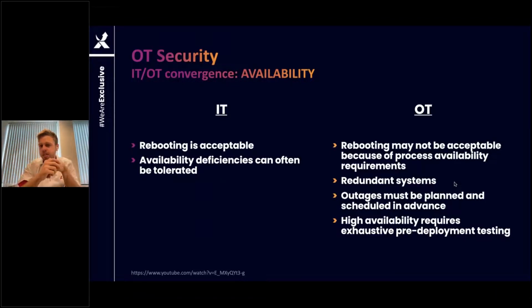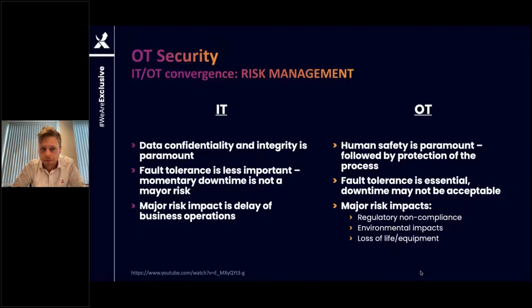You cannot restart an OT system right away. It must be planned in advance. And also the last point, high availability requires exhaustive pre-deployment testing. If you want availability, these systems are so well tested. They are designed and built for only a single purpose, and it's really important that they do that just right. So they are extensively tested.